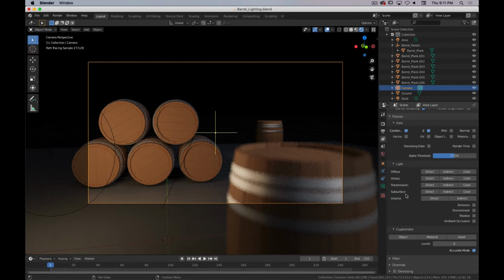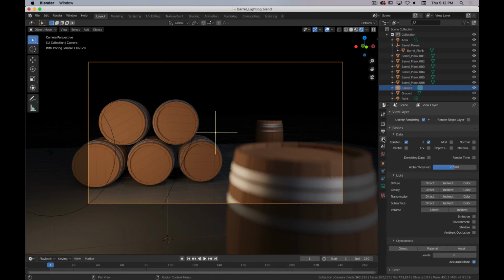This is the layer properties. In the view layer properties, we've got this denoising option. You can turn that on, and that'll save you from having to crank up the samples super high. For me, it saves some of my renders from having to go to 2048. I can render at just 1024 samples. I'm not going to worry about any of the settings in that. We're just going to leave it at the default. So that's in the layer properties, which is this one.